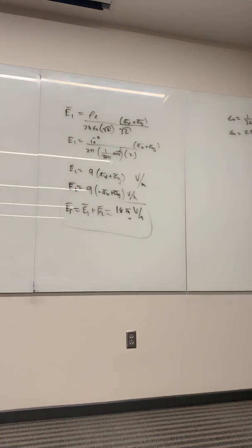Yeah. Now, I'm going to tell you, the 1 over 36 pi is a nice little trick to use for epsilon naught. 1 over 36 pi times 10 to the minus 9, because there's a lot of cancellation of the pi's and stuff. In the book, it says that 1 over 36 pi times 10 to the minus 9 can also be 8.854 times 10 to the minus 12. That's right up there. See it? Would you prefer us to use the 36 pi? Well, it's easier. The answers are going to come out about the same.